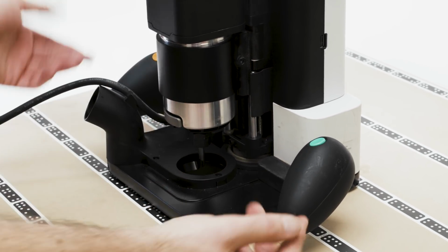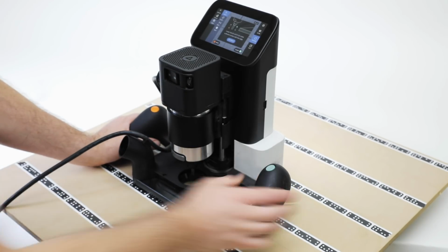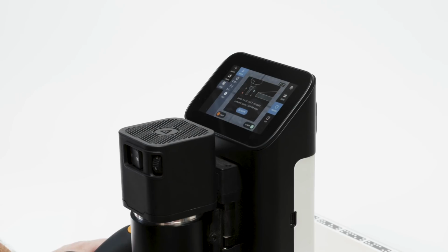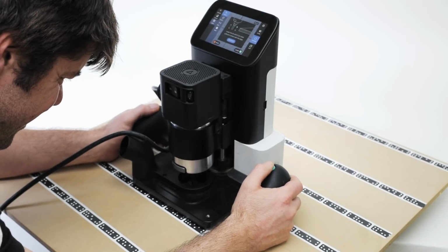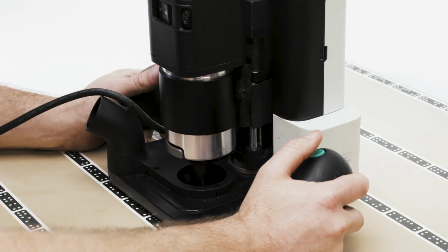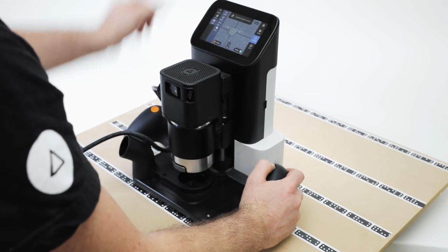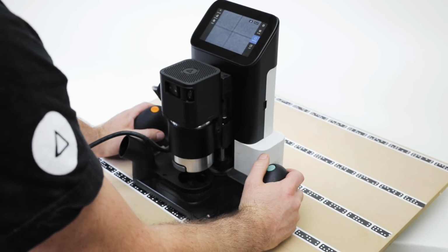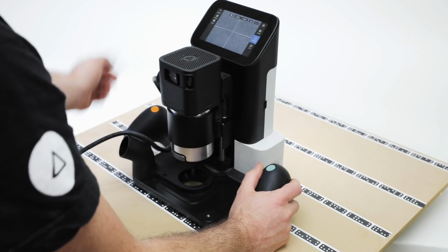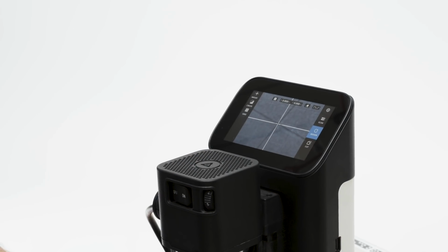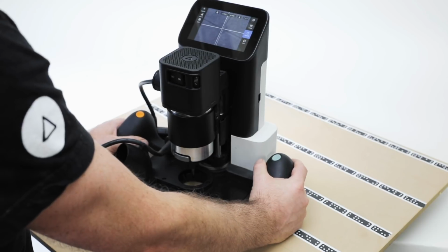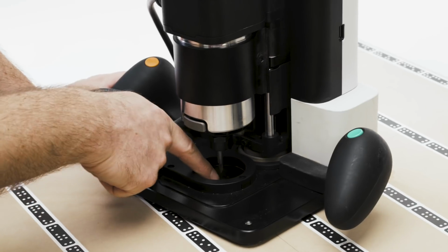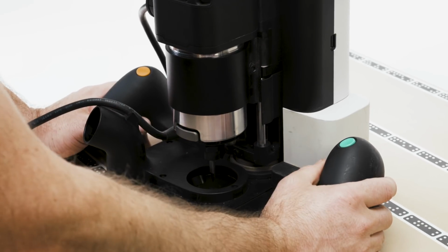So I'm going to do the same as I did in the previous one. Use an engraving cutter, lower it down until I'm satisfied that it aligns perfectly with a point down there, my pencil mark. Then I just hold everything still, double click the green button, and I get a grid where the 0, 0 point is exactly that point I referenced, and it's oriented relative to Origin. So that makes sense if you say just want to quickly place a circle or something like that. Something where the orientation doesn't matter, but the position is important.